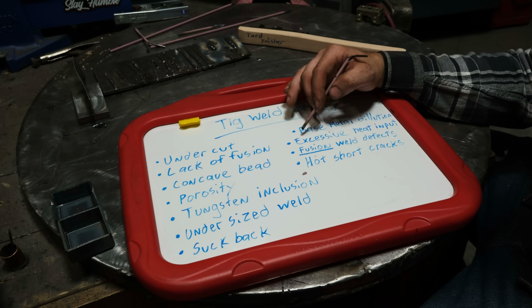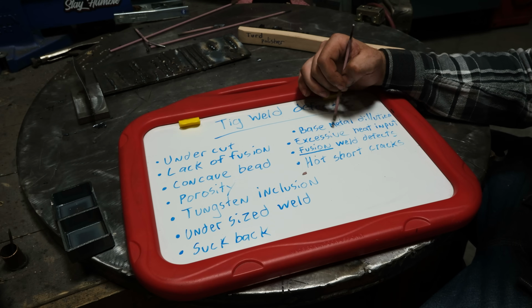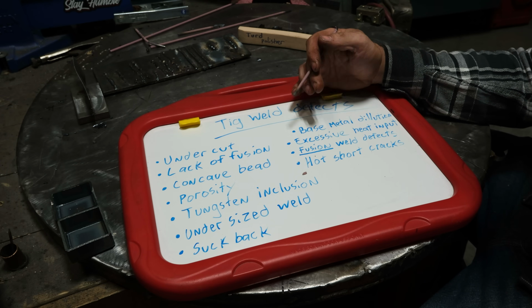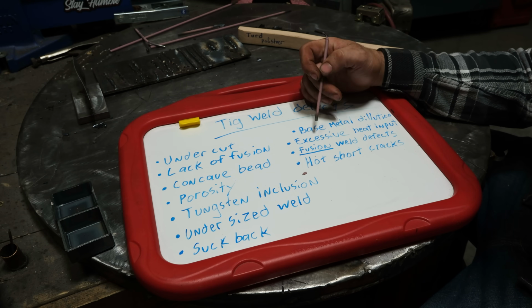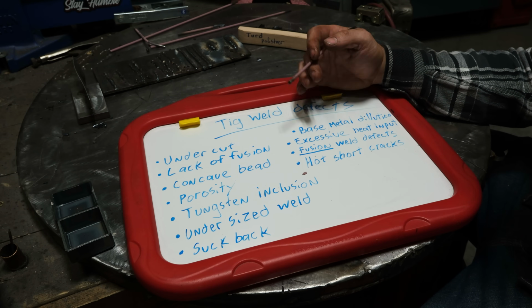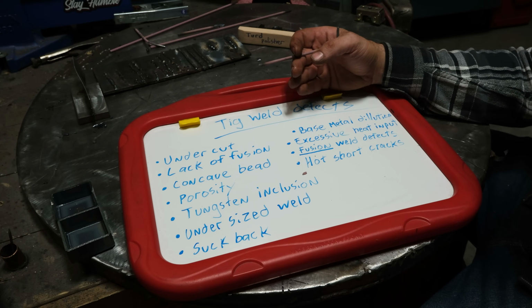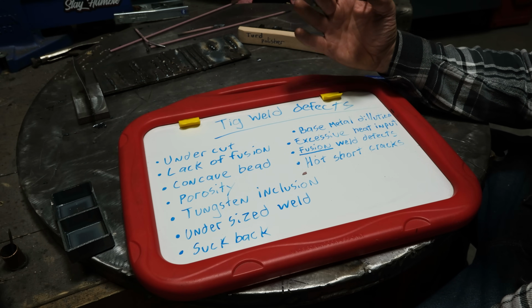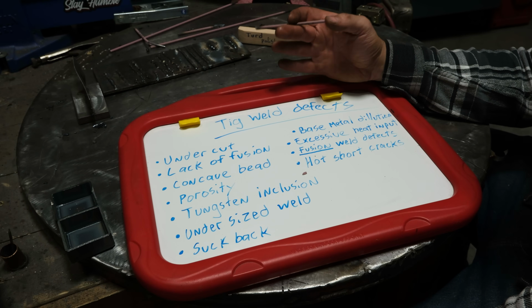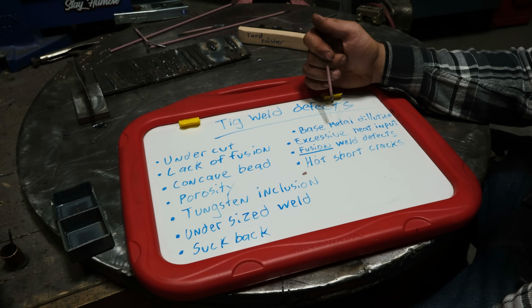Now, on mild steel, this is mainly an issue of poor grain structure. When you get into things like stainless, you will basically eliminate its ability to be corrosion resistant by cooking the chromium or creating oxides on the surface. So you want to be careful of that with other things too. So again, just use appropriate heat input.